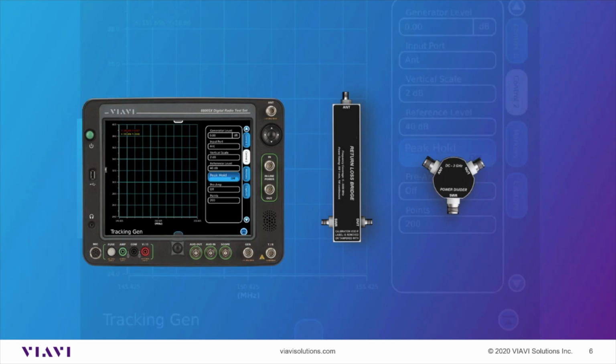If you had a high VSWR there, the power meter doesn't really give you a lot of information about why you have a high VSWR. So I think Mike may have mentioned this in his reply, but the power meter is a good way to initially look at that. Then if you take the system offline and use the tracking generator and the return loss bridge, you can actually sweep the system over a frequency. If you have a very high VSWR across your entire sweep, there may be an issue with the cable or a connector or something like that.